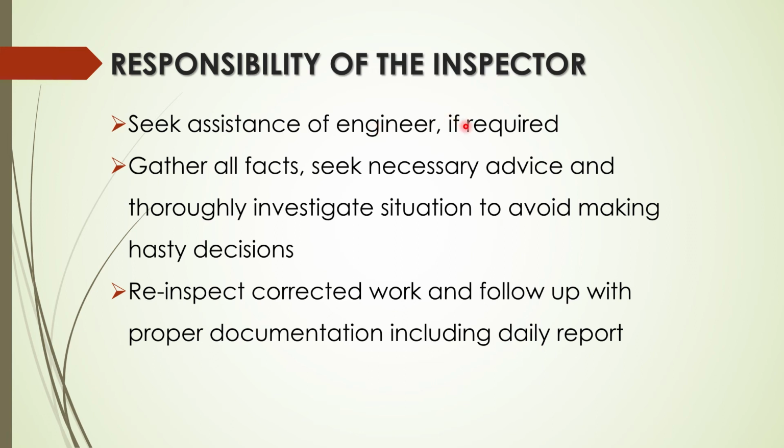Seek assistance of the engineer if required, gather all facts, seek necessary advice, and thoroughly investigate the situation to avoid making hasty decisions. Don't panic, everybody. Just gather your advice, take your time, get the facts, and do the testing in accordance with ACI, etc. Make sure you're doing it correctly, make sure your equipment is calibrated, and then you say, hey, we may have a problem. And if something fails, like a density test or a slump test, re-inspect the corrected work and follow up with proper documentation, including a daily report, to show that this failed, but the contractor did this at this time, they fixed it, I retested it, and the test passed. So that's very important.